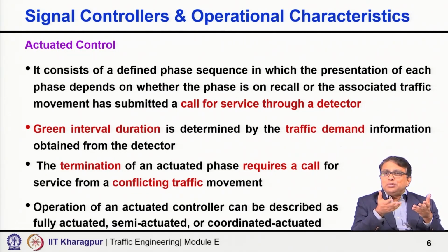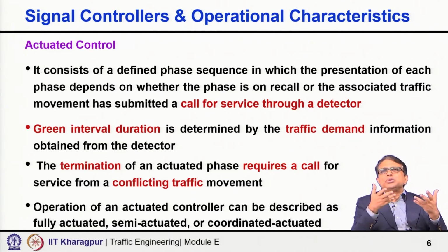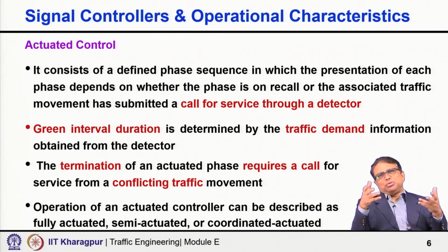Actually, maybe many of the time there is no vehicle. So, the green is actually wastage. So, in that case, if we can do actuation to handle that particular traffic movement, then we can optimize the overall signal setting or make the operation even more efficient, right. So, in that case, detection could be in one approach, detection could be in multiple approaches, a variety of actuation is possible, but always it is actually to make the system more efficient.